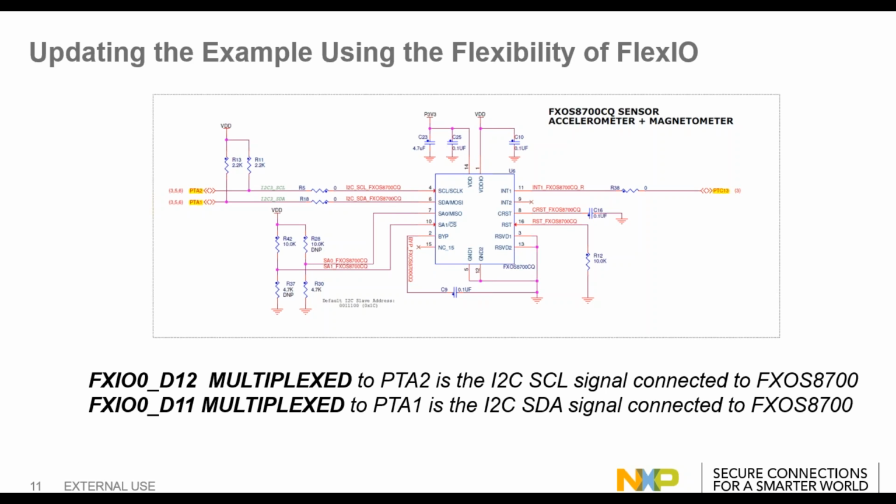And FlexIO D11 pin is also on PTA1. Just to demonstrate the capability of the FlexIO, we can take this example that is already in the SDK. It works right out of the box to demonstrate the FlexIO interfacing through I2C to the accelerometer.